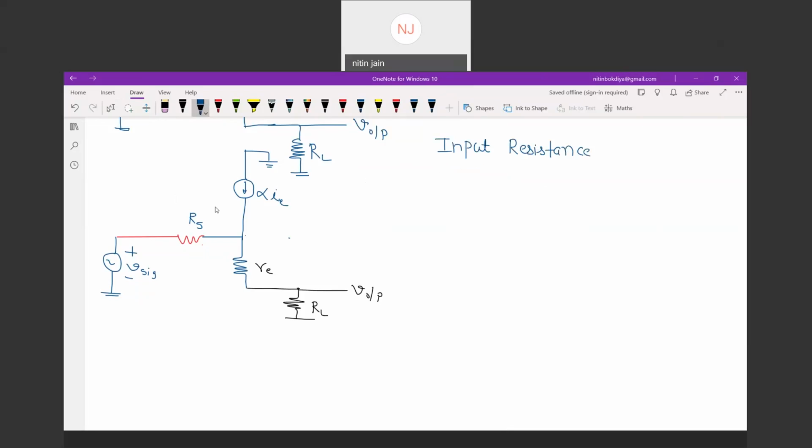So you can say this is input resistance. Remove the supply and see what you find. This is input resistance, but believe me, this is very important for this analysis, that input current is base current and here current is emitter current. So you can say input voltage is what? The voltage which appears here is input voltage. So you can say V input divided by base current is the input resistance for this amplifier, and you can say